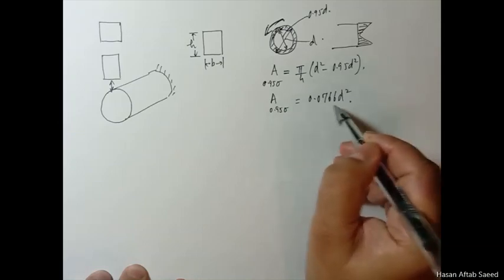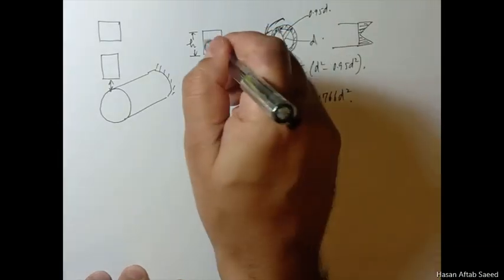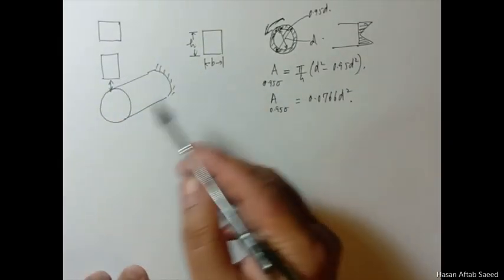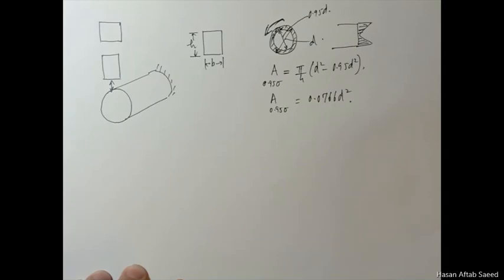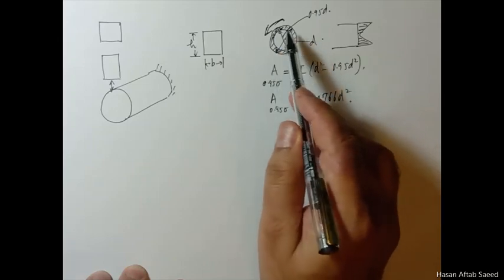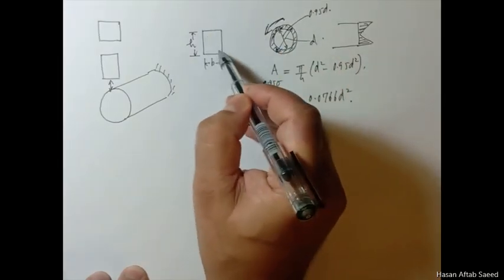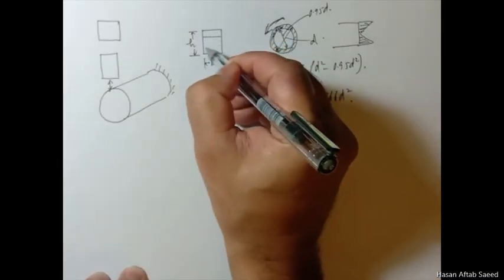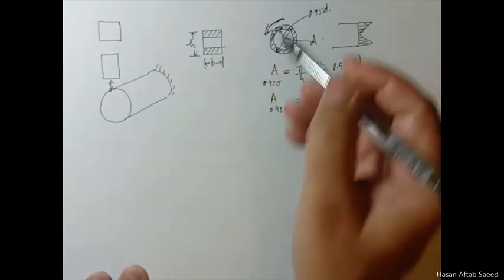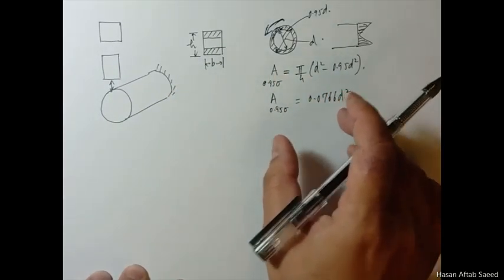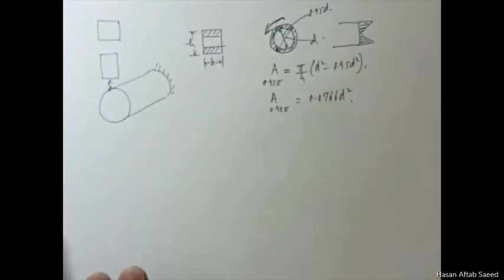We equate this area with the area of all these situations, non-circular members or non-rotating members, so that we compare this area, the 95% stress and more stress area, to the area in all these sections which bear 95% or more of the maximum stress. We'll just equate these two and find out what is the equivalent diameter in terms of this that we can use in that equation.